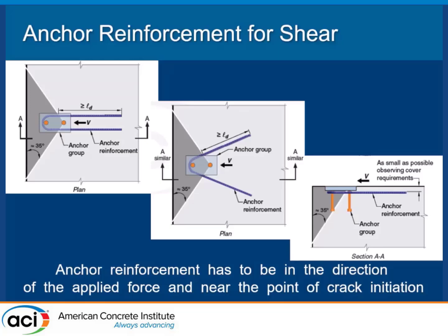Now, the great thing about shear reinforcement is if you're casting in place, so it's fresh, new construction, and you use a hairpin, for those of you who don't know what a hairpin is, you're looking at it. We use them to spread out localized stresses in concrete all the time. They're wonderful.